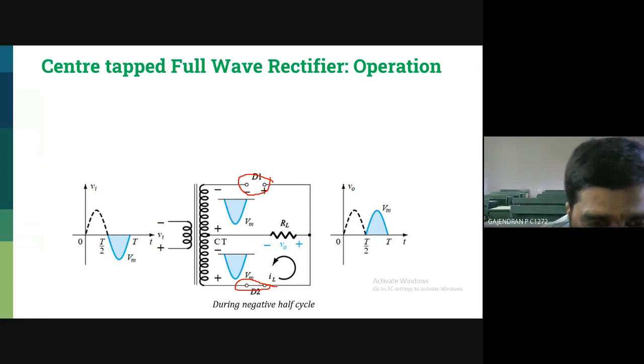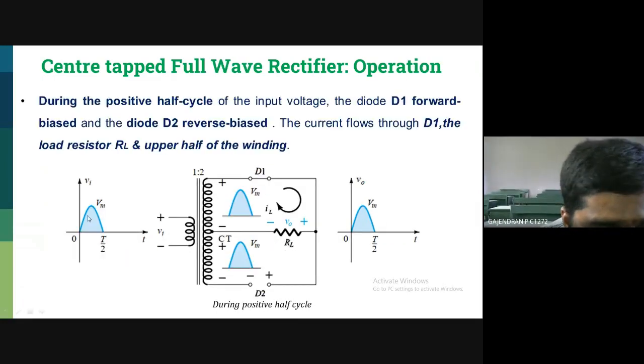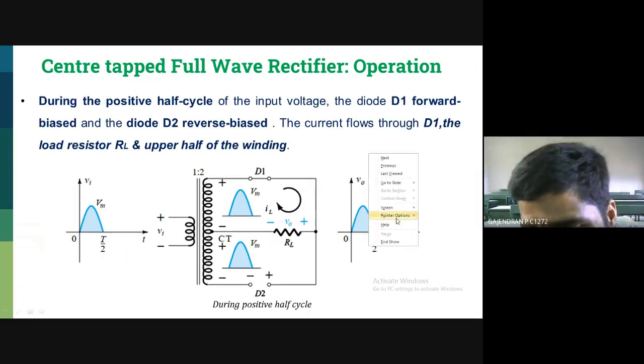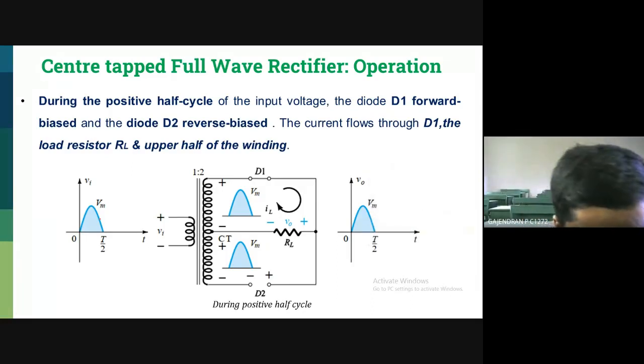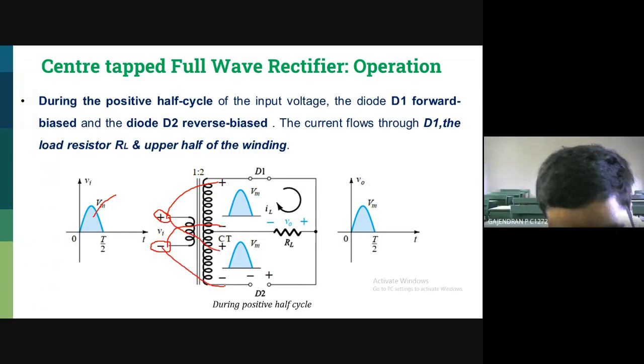Okay, please see the polarity. For an alternating waveform, we don't have a polarity, but to specify the positive cycle, we mention the first terminal as positive and the second one as negative. The corresponding voltages appear in the secondary winding with respect to my input as positive and negative.